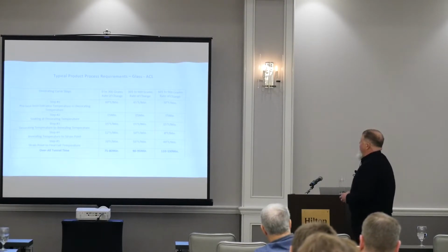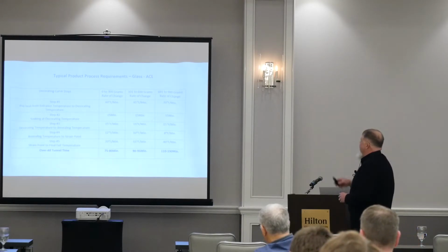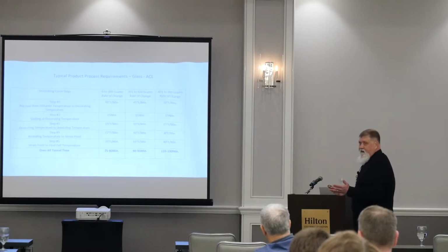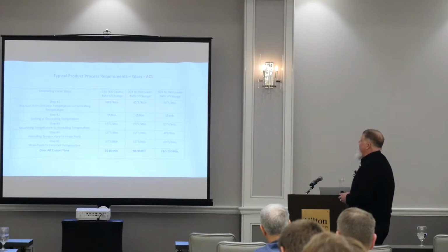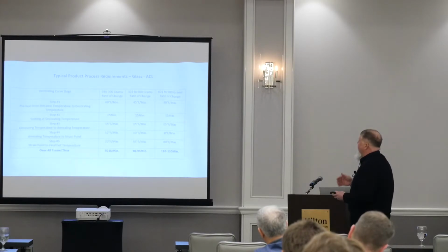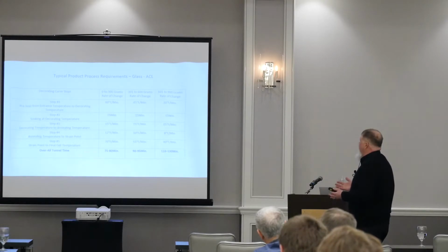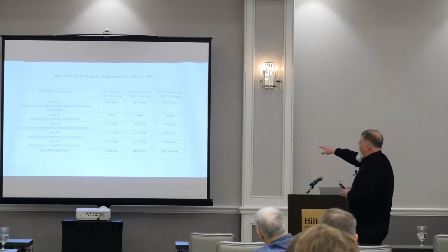Your next step down is your curing or soaking time. For this example, I've got 15 minutes. That's going to vary somewhat based on the product that you're using. From that point with glass, you've got to take it from decorating temperature to annealing temperature, and I'm using roughly a 15 degree F per minute rate for all those products, because what we're trying to get to then is